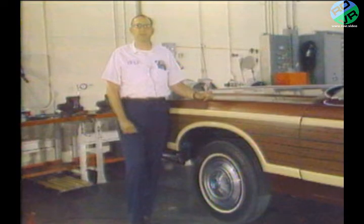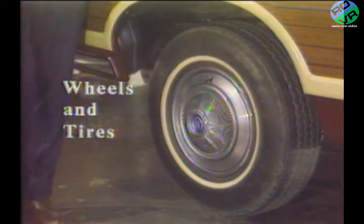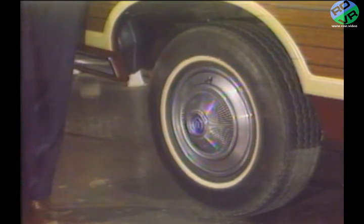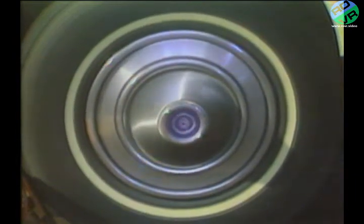Now that we've reviewed some basic NVH background and the importance of a complete road test, let's first look at NVH problems associated with wheels and tires. Noise and vibration problems with tires and wheels occur because out of round or out of balance wheel assemblies try to alternately lift off the road surface and slam down on the road surface. This lifting and slamming of one or more wheel assemblies can be clearly felt by the driver and passenger. In severe cases, the hood and fender sheet metal can even be seen to vibrate.